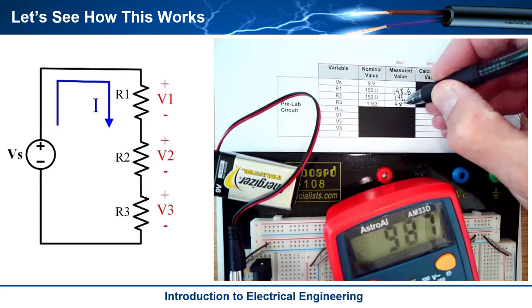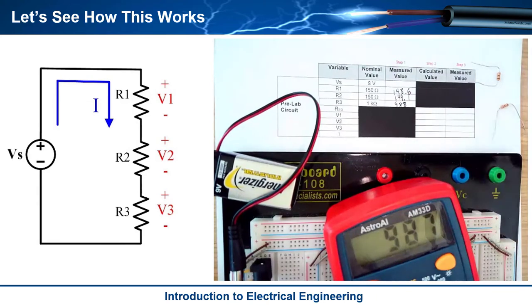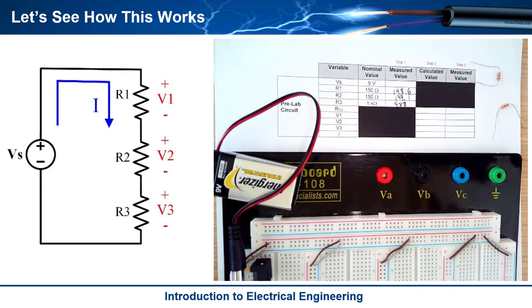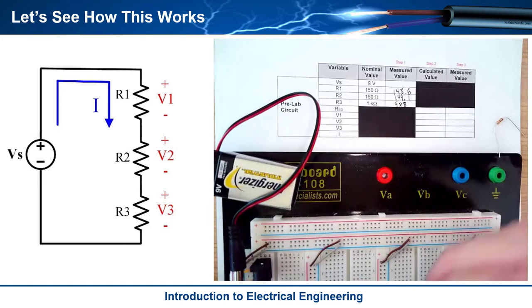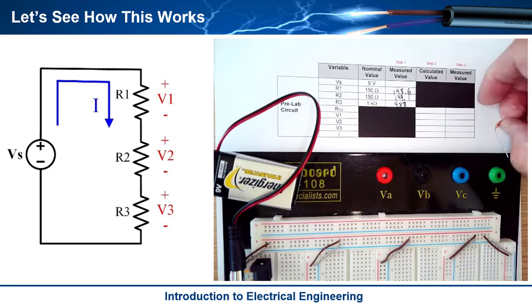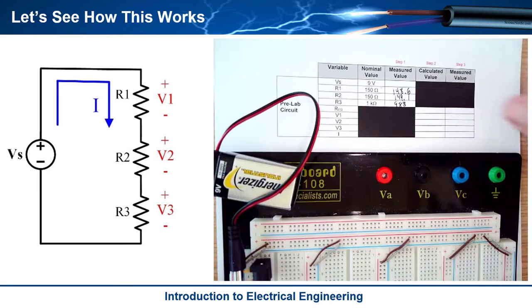All right, so now I want to measure the voltage. But remember, batteries, their voltage drops the more current you draw out of them. So I have to actually have the circuit itself built in order to know what voltage I'm going to have. So this is circuit analysis, right? So I know what I have. And so what I'm going to do is I'm going to keep these 150 ohms straight.